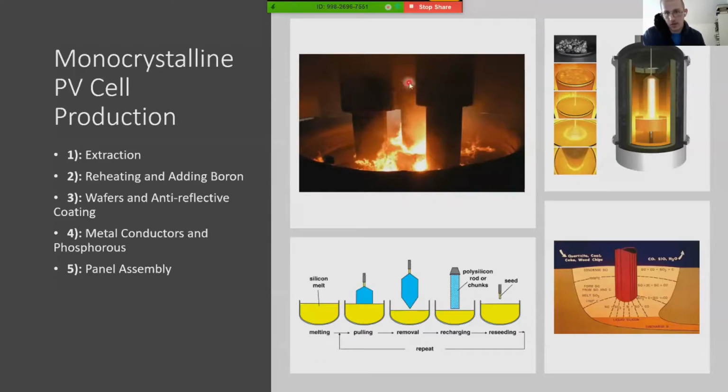Basically, these are three electrodes that are carrying a lot of power, and they get inserted into the sand and they melt it. And this is kind of a cross section of that process. As you go farther down into this pit, the temperature gets hotter, and that heating process also purifies the silicon and gets rid of impurities, and then the pure liquid silicon is discharged.